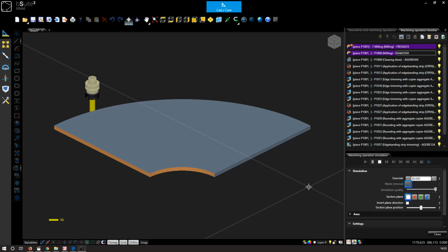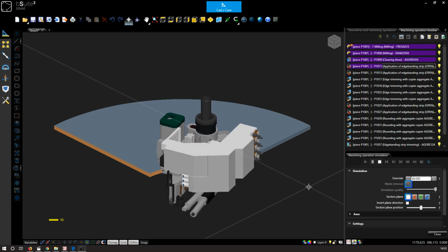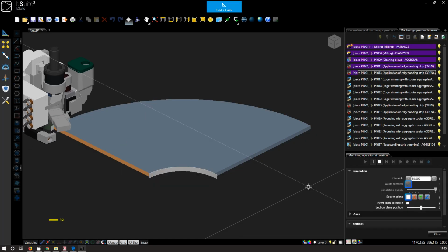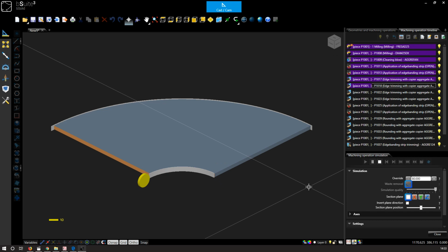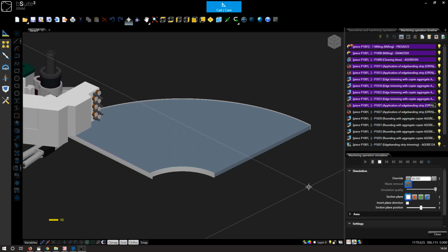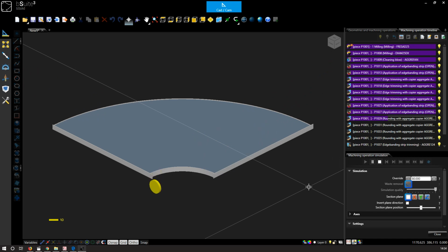So this is using a 5-axis machine with an edge banding aggregate, and because in the part in imos we told it that it should be edged on the CNC machine, it knows to then blow off the dust and then come in and apply the edge banding strips piece by piece. So we've done edge 1 and edge 2 here. We need to trim these off, so the trimming saw will come in, trim these flush, and then we can apply the remaining tape. Okay, trim them again, and then we will trim the tape flush with the surface. This looks good.